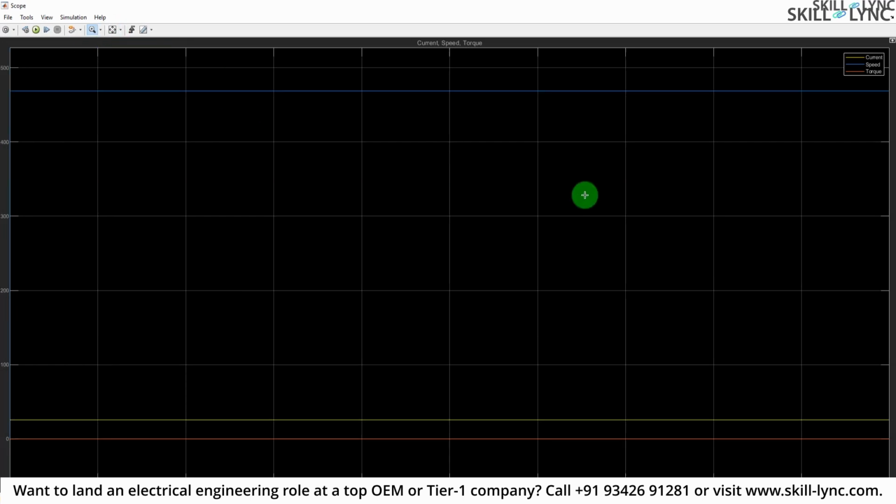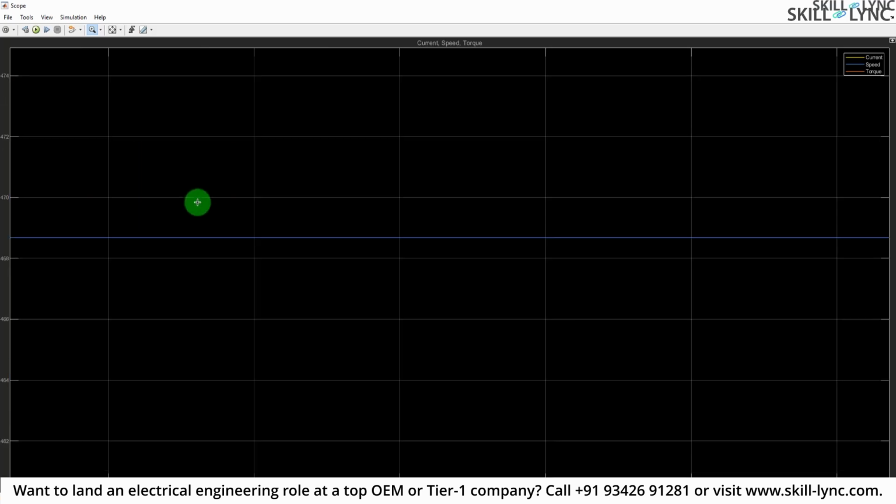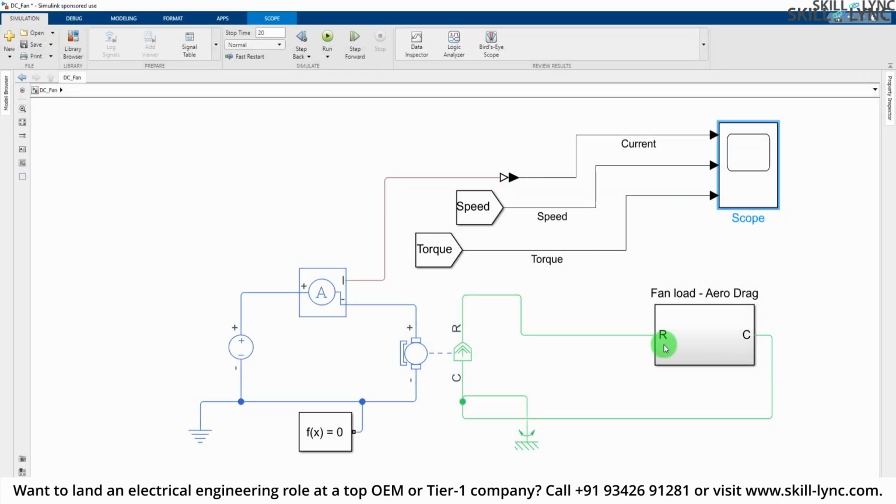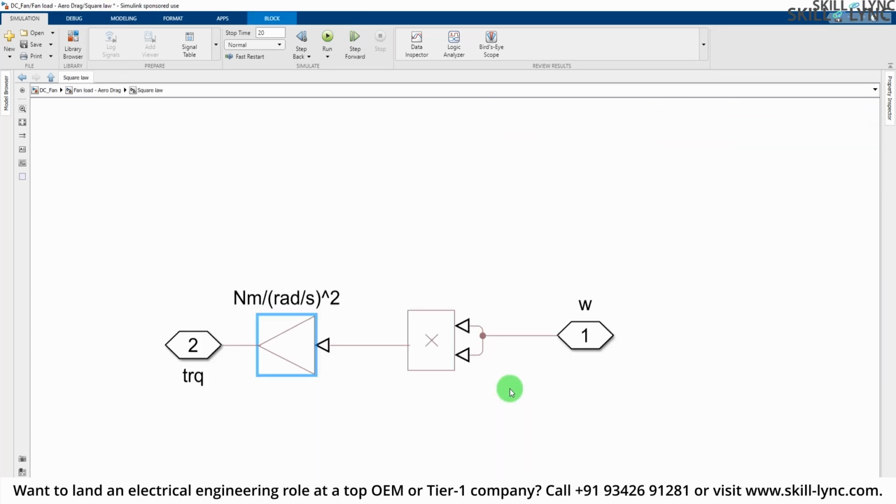So what has happened to the speed is now almost constant. Because of the inertia, the speed was gradually increasing. But now we have this RPM, let's say speed unit, of around 469 units. So this is the effect of inertia. If you change an equation in this subsystem, or maybe the gain, and you want to implement some equation like 3 plus omega m square or 3 plus 2.3 omega m square, you will be able to do it.